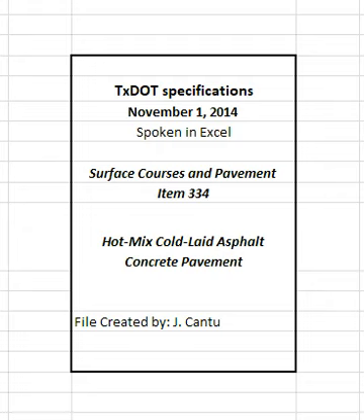2.3 Baghouse fines. Fines collected by the baghouse or other dust collecting equipment may be reintroduced into the mixing drum. 2.4 Binder material. Furnish asphalt binder, primer, additives, and water, unless otherwise shown on the plans. 2.4.1 Asphalt binder. Provide the asphalt shown on the plans, meeting the requirements of Item 300, Asphalts, Oils, and Emulsions.